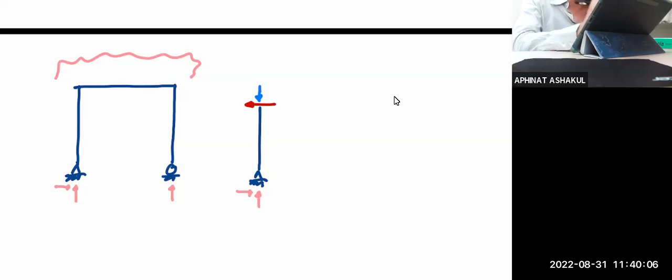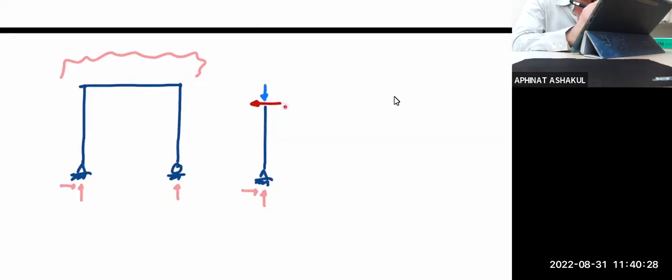Okay. So now I cut the free-body diagram of the first one. You see that the reactions are already there. In order to maintain equilibrium of this free-body diagram, you probably know that you have vertical axial force equal and opposite to the pink one, and then you have the horizontal shear equal and opposite again to the pink one.